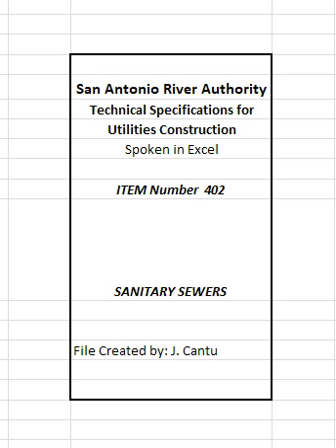9. Prestressed concrete cylinder pipe. Prestressed concrete cylinder pipe will not be permitted for use as sanitary sewer transmission line. 10. All sanitary sewer pipe and fittings shall be tested and stamped by an independent testing laboratory or the San Antonio River Authority. This independent testing laboratory shall provide a certificate of compliance to these specifications that shall be signed by a registered professional engineer. 11. Mechanical or compression joints, concrete jointing collars, or non-reinforced rubber adapters shall be used only as approved by the owner. 402.3. Construction methods.